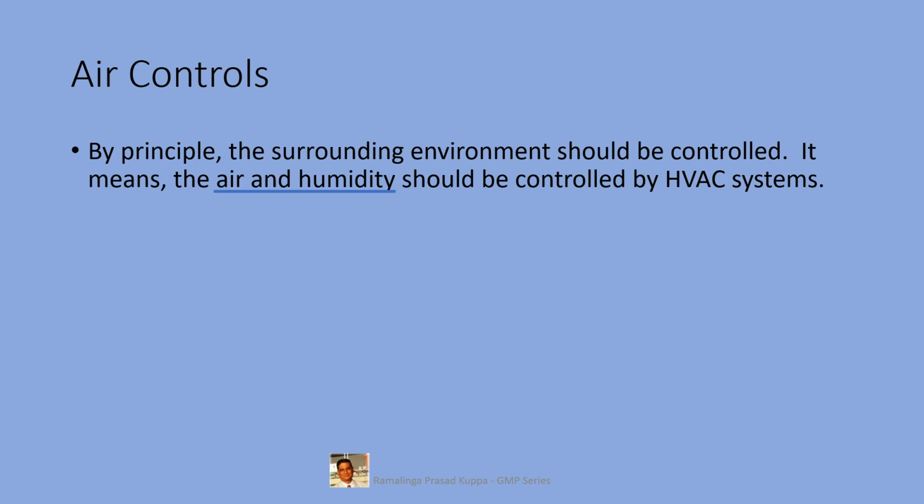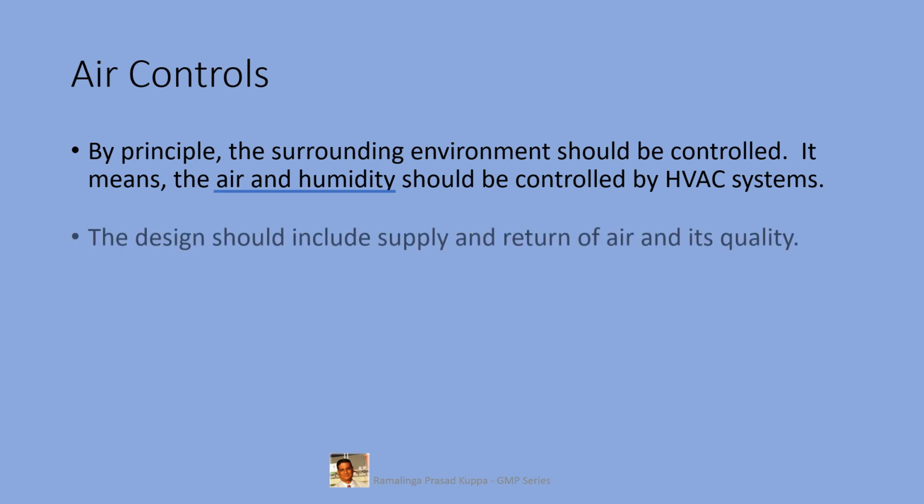So in closed rooms, effective flushing with fresh air is required for comfortable working conditions. Also, too much humidity in closed rooms would suffocate the operator, and of course the product quality also will be impacted by inappropriate humidity conditions. Temperature control is also necessary for the air coming into the closed rooms.